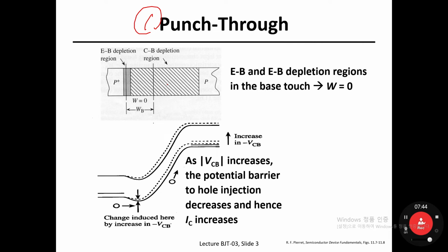So what is punch-through, by the way? Punch-through happens because of the extended depletion layer coming from the metallurgical junction, leaving no quasi-neutral region behind. In the case of a PNP BJT in the common emitter configuration, holes are injected into the base region and diffuse out toward the collector region. If these injected holes successfully go through the quasi-neutral base region, then we may expect a saturated output current for a given output voltage.